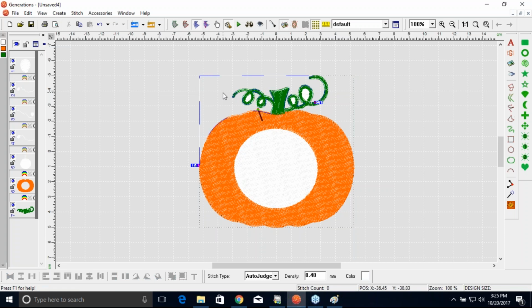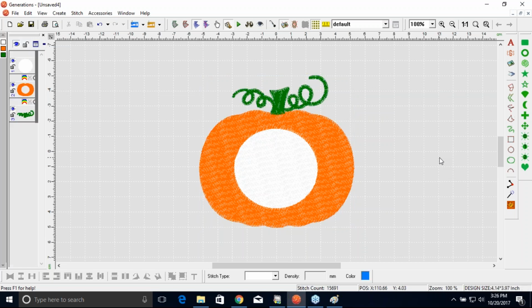I'm going to right click on this area, hold my control key down, and I'm going to hold my control key down while I right click on these other areas. I'm also going to include the inside white areas of the vine. Right click and right click. And then while holding control, hit delete on the keyboard. Not backspace, but delete. So now you can see that we accomplished the same outcome as we did with that other one being a scanned image. So sometimes, this is why I say sometimes I bring in designs several different ways.